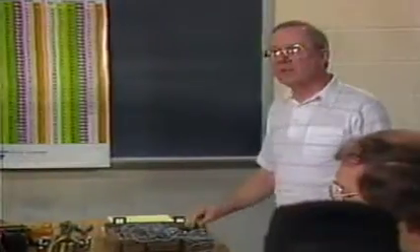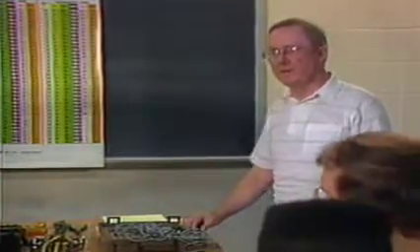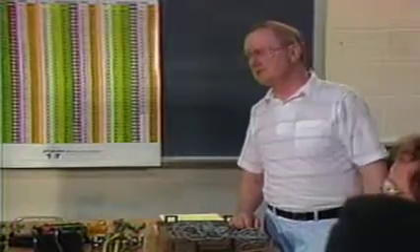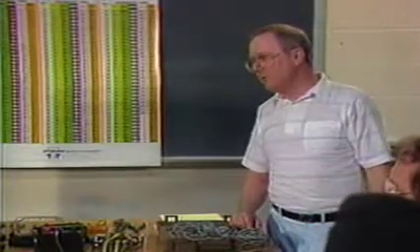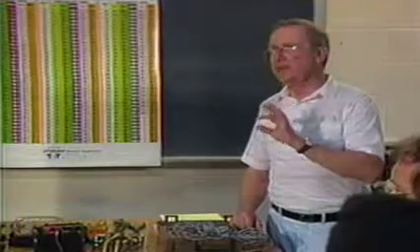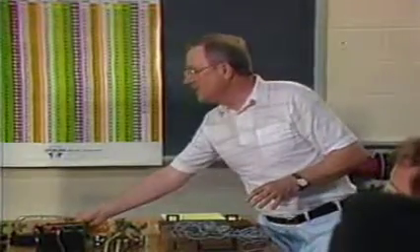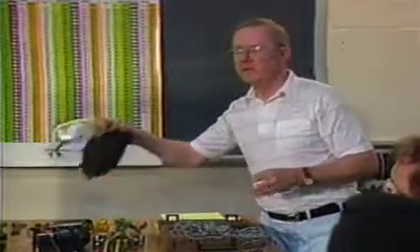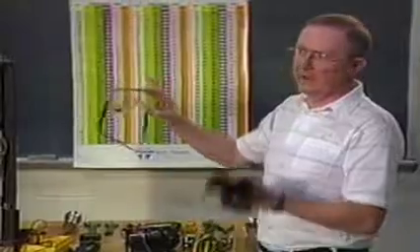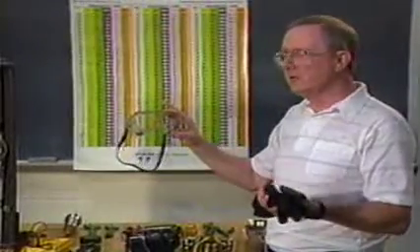Now, while using these instruments, we must be very, very careful. We must be very conscious of safety. The first person you want to save is you. When we handle high-pressure refrigerants, we are either handling them in the liquid state or the vapor state. In the liquid state, we're subject to burning our fingers severely from freeze burn. We should always wear goggles and gloves when working with refrigerant in the liquid state.